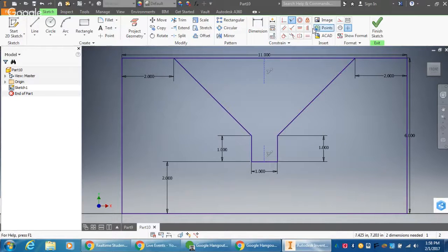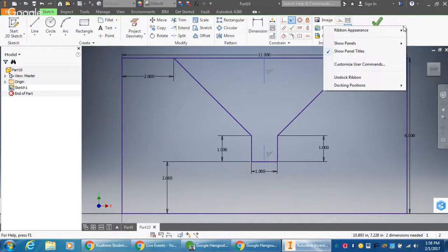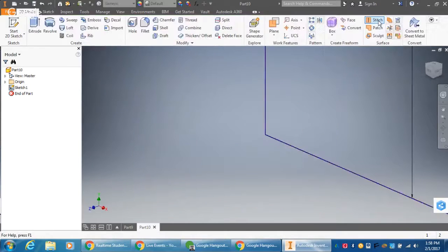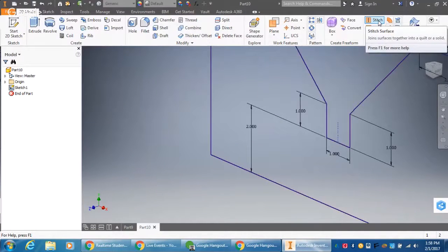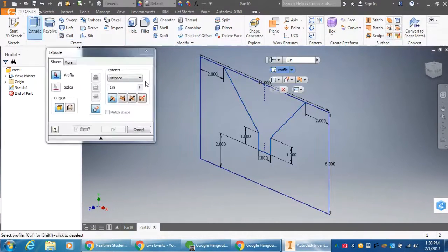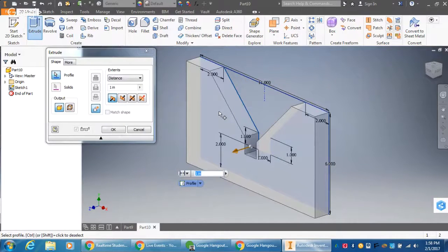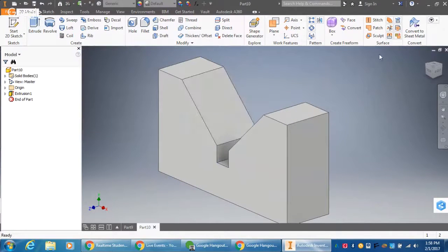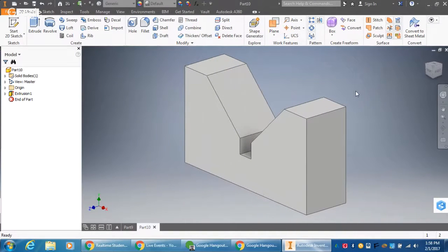These are all my geometric constraints, or I can use numbers to constrain my geometry the way I want. Now I have the shape I need. All I've got to do is extrude that out 3. Let's see what happens when I go to finish my sketch. And yes, I know I'm right-clicking because I'm on a trackpad. Hit home. I'm going to extrude just that portion. 3, enter, and we are done. So we've used some geometric constraints now, as well as some dimensioning constraints. Those are very helpful things to keep in mind on how to get this stuff done.